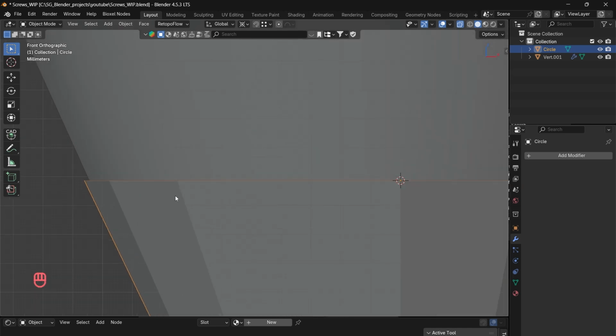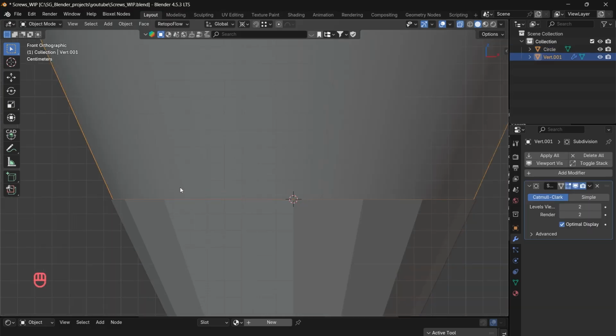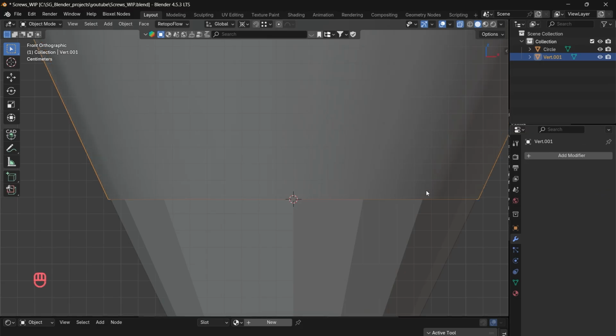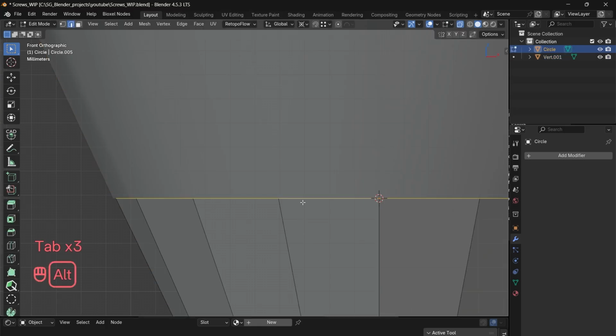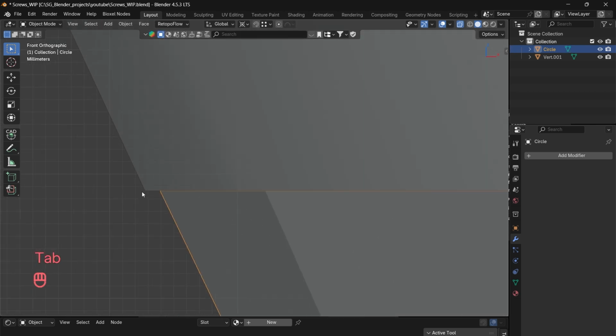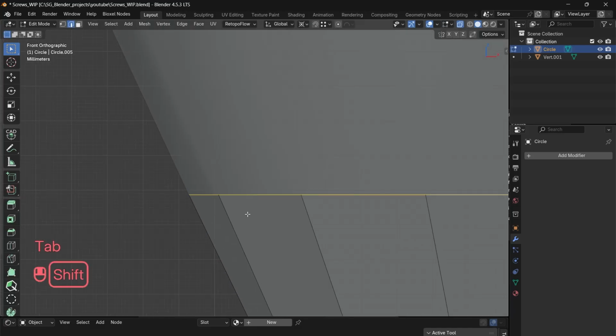As I mentioned, this is the pitfall of using 16 vertex. When you try it with 32 vertex, you will not see this. And for this one, let me disable that subdivision modifier, because now I already have it with 16 vertex, and this object also has the edge with 16 vertex. So what I need to do is just scale it a little bit so that it matches and gets properly aligned to this edge, right? So that when I merge these two, they will not cause any issue.